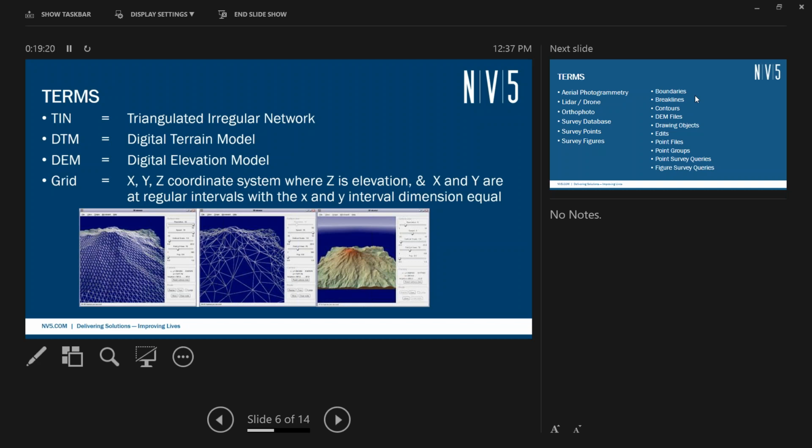They're the same surface, but one implies more accuracy. Okay? We don't use the DEMs for that reason, because a lot of times they apply an accuracy that isn't actually there. Okay? A lot of times it's also based on elevations that are spaced out 10 meters apart, and so the density of the data is not there. Okay? So a DEM is based on a grid. The grid sometimes, most of the time, is square, but does not have to be square. Okay?